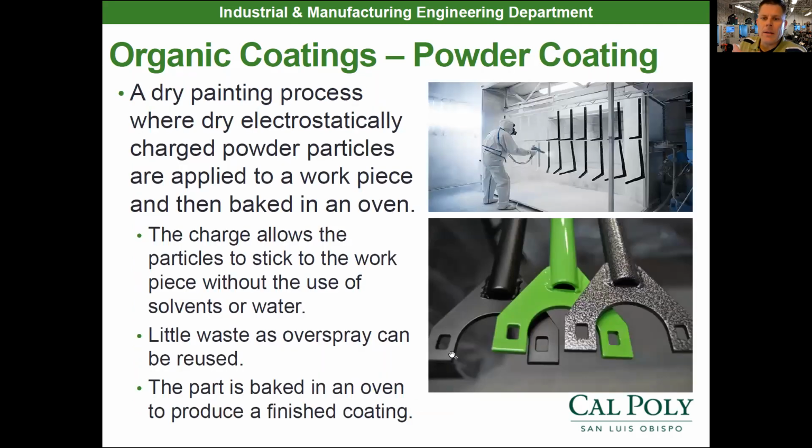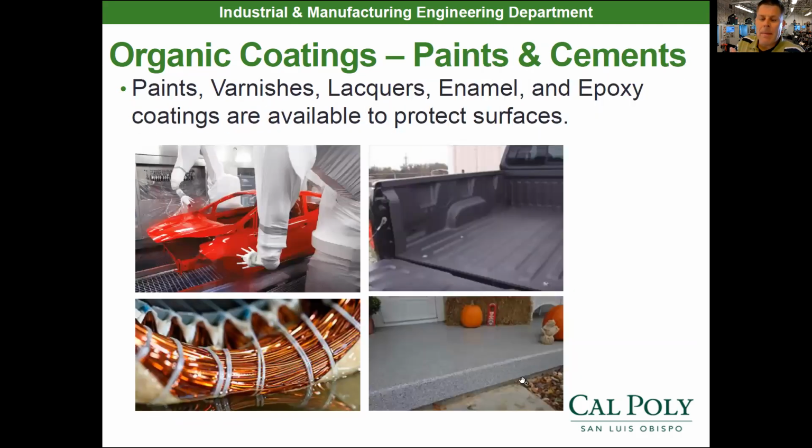With these organic coatings, you want to make sure you clean the surface very, very well before you apply any type of organic coating, or else it's going to bubble up or have an issue afterwards.